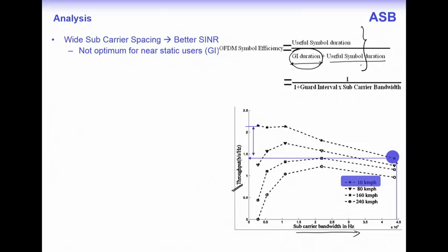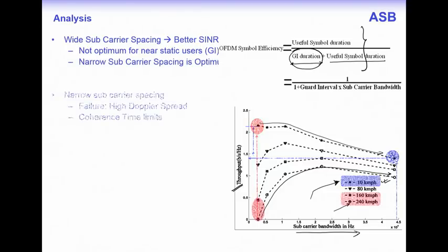So, that is what we find, that if you are maintaining a certain subcarrier spacing and you are simply studying the effect of different mobility conditions, we will find that the throughput would decrease as one increases the subcarrier spacing, but one maintains certain mobility conditions. Okay. Whereas, in another situation it initially increases, then more or less remains the same up to a certain point. So, we go beyond this and look at the overall structure.